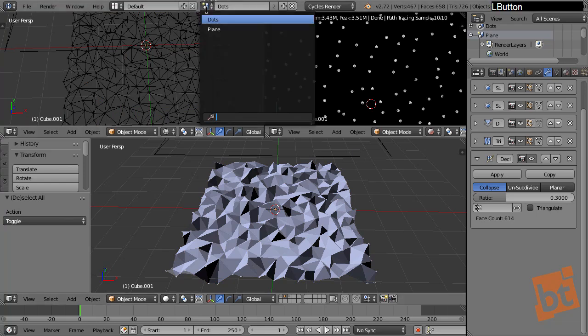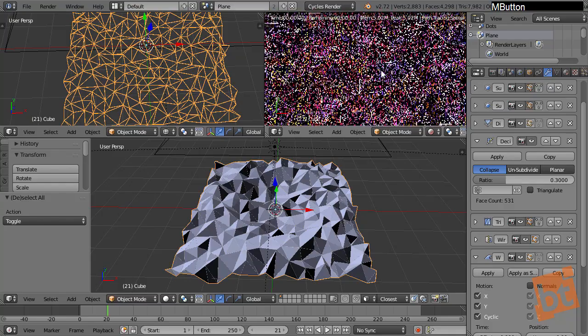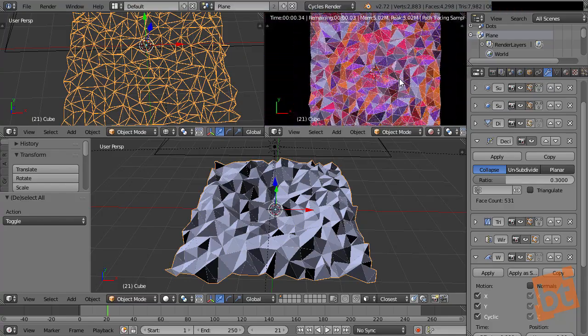Probably someday we will have the ability to link modifiers, so they are kind of instanced, because dupliverts are kind of tricky, because you actually need a different mesh, because otherwise the mesh disappears on render, and we don't want this, because this is the main thing of the image, which is the plane and the wireframe. So yeah, that's it.